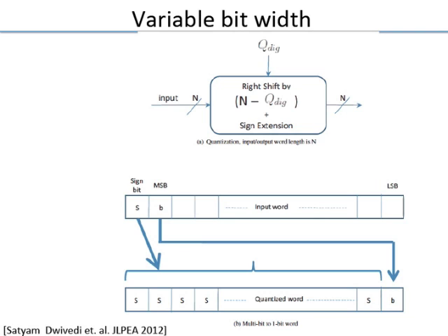You make sure the other bits you just put to a static value, possibly 0. So that's all. Nothing is being said about standards compliance or non-compliance or anything. It's just a way by which you can reduce this effective switching activity. Alpha i Ci product, in some sense we are reducing. Or alpha i we are reducing to 0 for some of the i's, essentially.